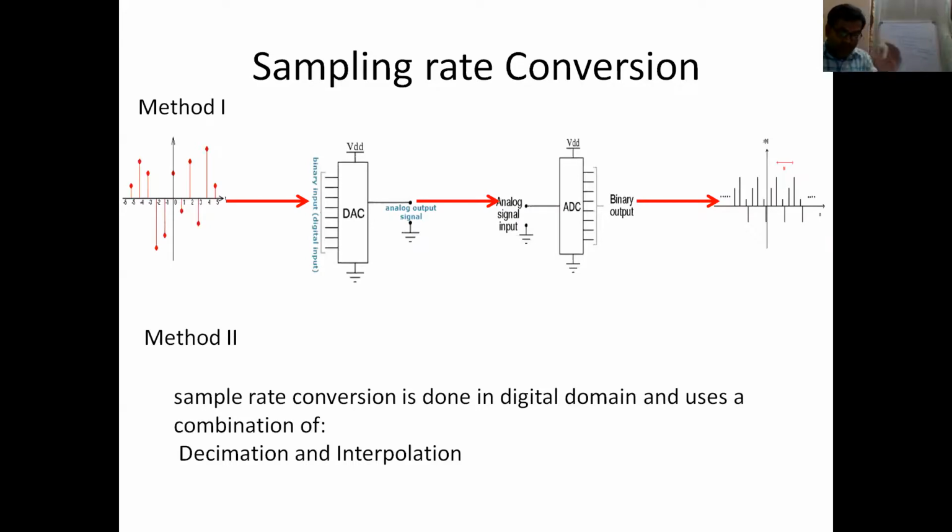That means where you have this digital data initially, you would have sampled with some sampling frequency. Now the second time that you are sampling, it will be sampled with a different sampling frequency, and you have converted into digital again. Let me give you an example. Initially you have sampled your signal that was present in your CD with 44.1 kilohertz, let us suppose.